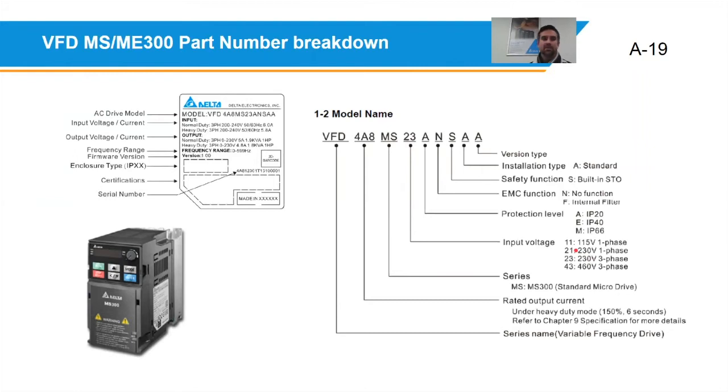It will have 2 connections, star and delta, most likely. You need to connect it in delta, which is a 220 volt three phase connection. Typically for 400 volt motors, the typical connection would be star. Again, this is a general rule. It's not a blanket rule. You really need to look at the motor's nameplate to decide how that connection would go. Hope that answers your question.